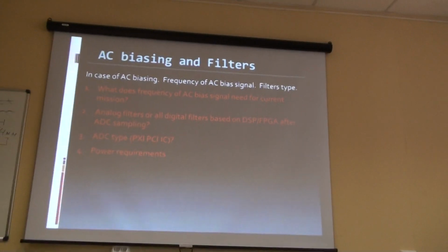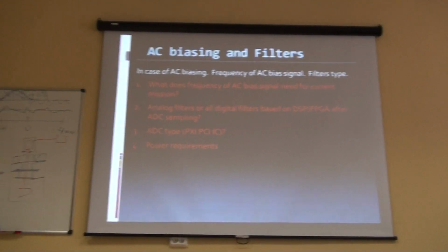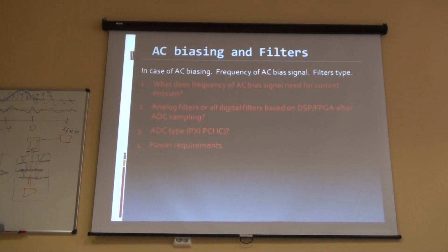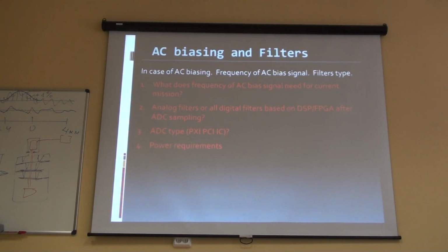The next question is, should we use DC biasing or AC biasing? Yes, I think we should, in the first approach. But we need several bias oscillations per sample. Which means that the AC bias frequency should be, say, 200 Hz or so, minimum.